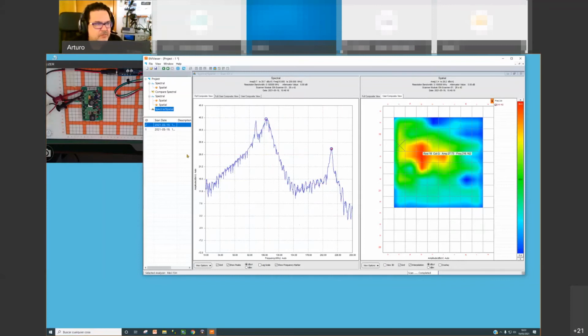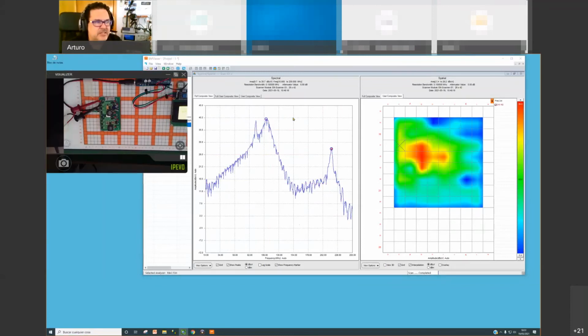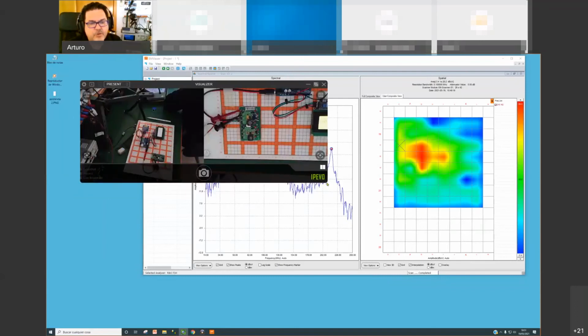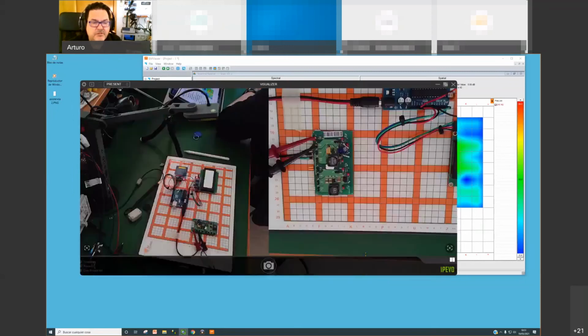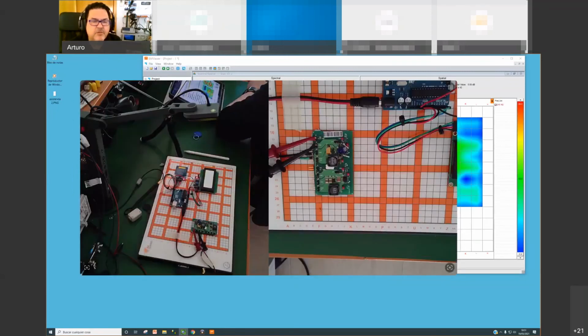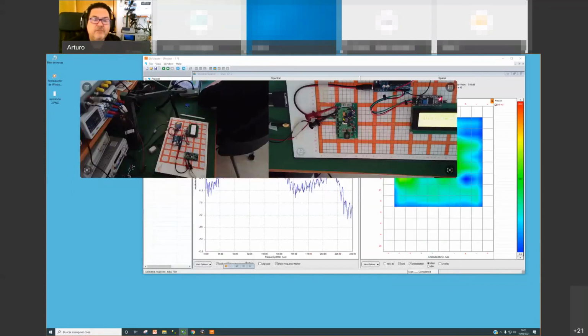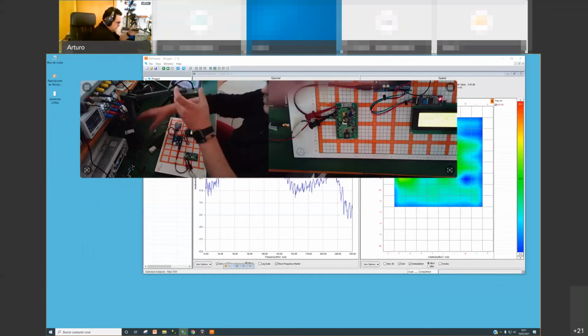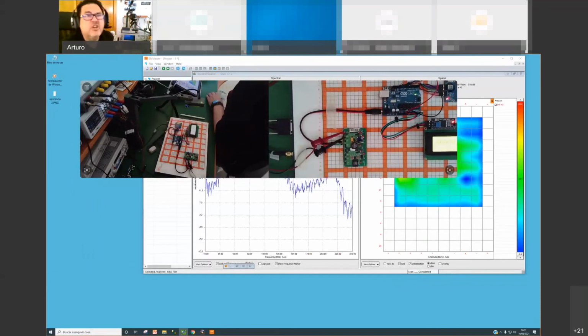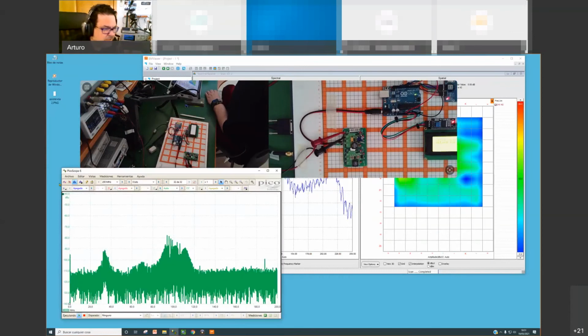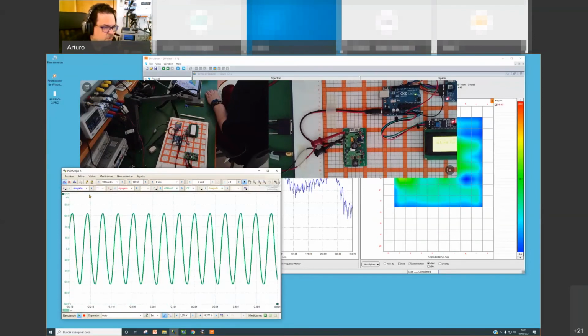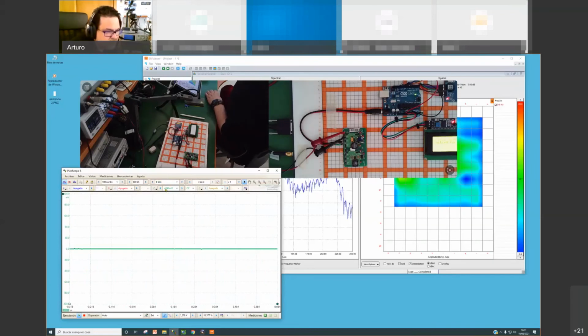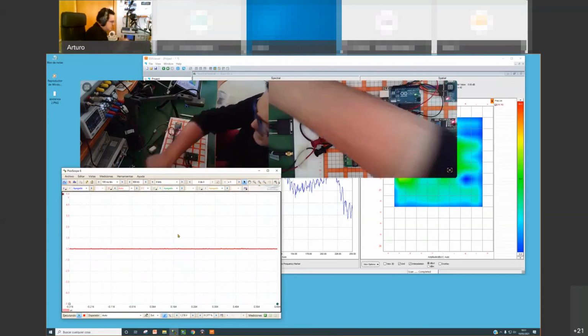So in my opinion, when I have finished the analysis of my system, I have a hypothesis. The idea is that I consider that the problem is coming from the DC-DC converter, and that is because I am radiating to the environment. So let's go to the circuit, and let's go again to the oscilloscope. We put the oscilloscope in this way, here, and let's go here to the time domain. We are going to go to the second channel B. Let's put in auto, and let's see how the switch is working.